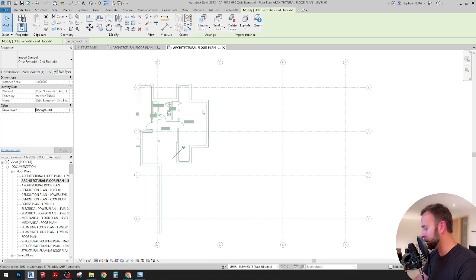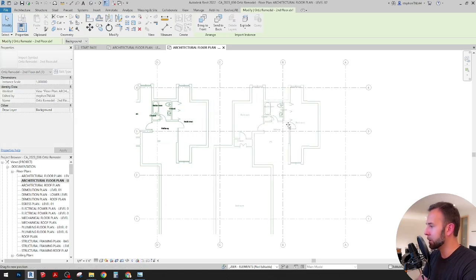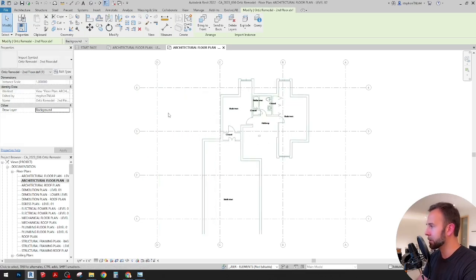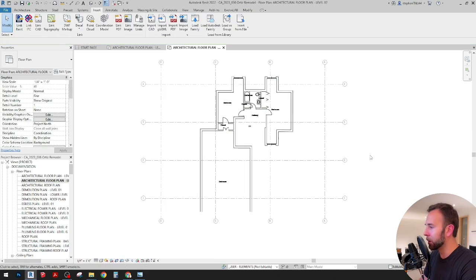So, and it's pinned, so if you do not select pin objects, you'll have to remember to change that in your modify tab there over to the left. So I'm going to select it, unpin, drag it over to the center, and I have this model or template file in Revit pretty much started already for all new projects that have the grid lines already in there. So it's easy for me to just navigate to a level 2 and drop this in there, and we're ready to model.